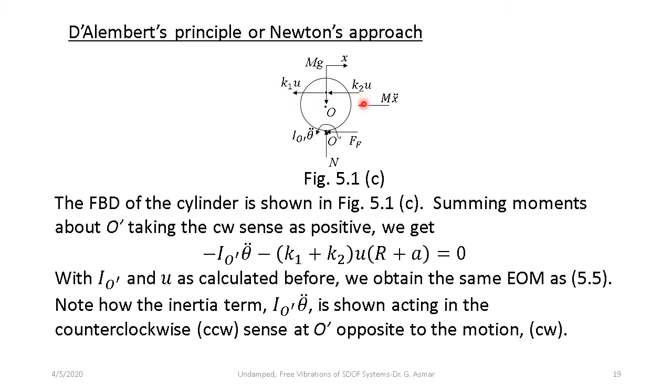I have the friction force FF, which I choose to have it act to the left. This is an arbitrary choice because FF as of yet is unknown, which means that I can simply assume its direction because I don't know it yet.